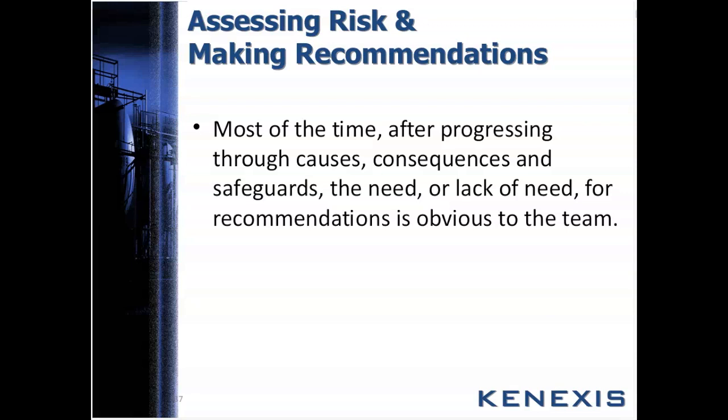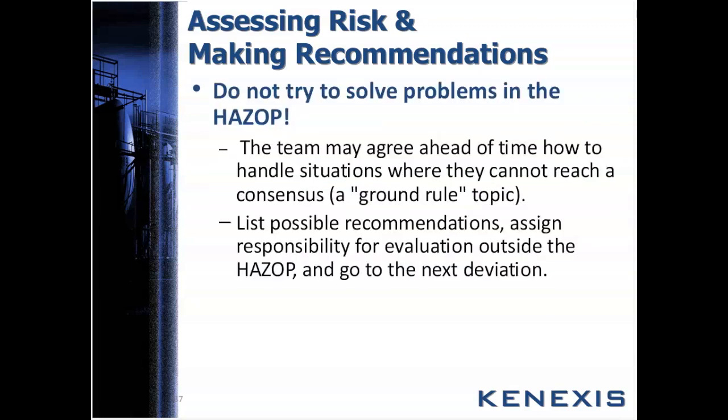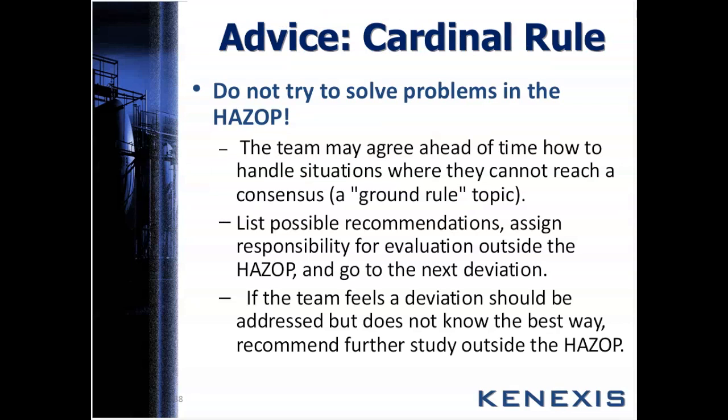Sometimes it can be very difficult. But sometimes you just say, hey, let's shelve this, or move the recommendations aside for further study. Recommend a better study, where you've got a better understanding, and move on. Okay, don't try to solve problems in the HAZOP. Hard to do, but nevertheless, that's the cardinal rule.